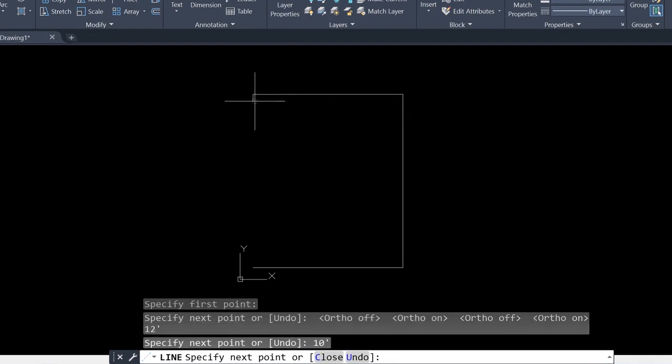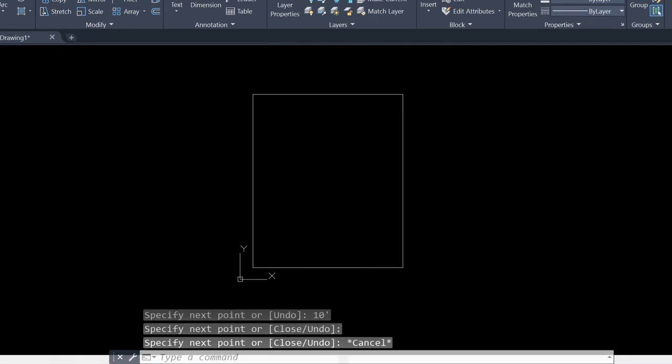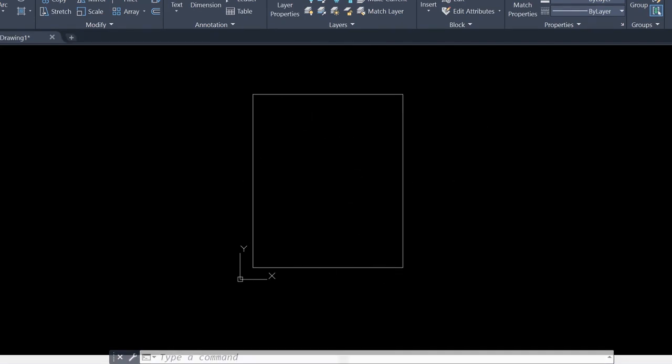feet. And then I'm going to drag my mouse down, and there you can see it's going to snap to that end. I'm going to click, and then now I've closed in all my walls. Congratulations, you have created your first shape in AutoCAD or room. But before we actually go out and celebrate, let's add a little bit more detail to this drawing.